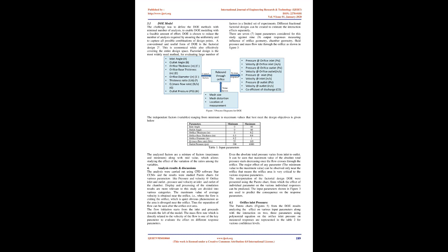The boundaries are created at the inlet and outlet of the domain to specify the boundary conditions. A unique solution is defined by the boundary conditions, and the properties which can be included in the boundaries are pressure, velocity, etc. In the present model, the mass flow rate is defined at the inlet and the pressure is defined as the outlet boundary condition.